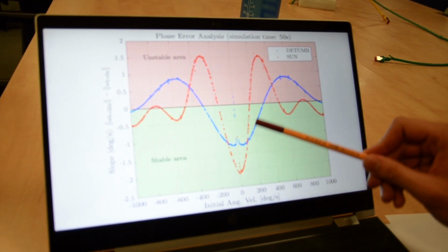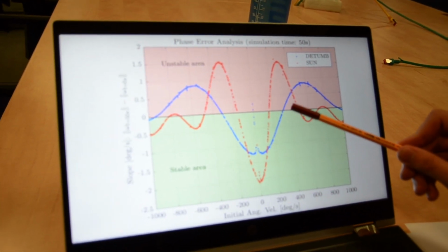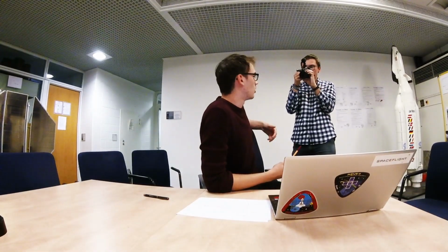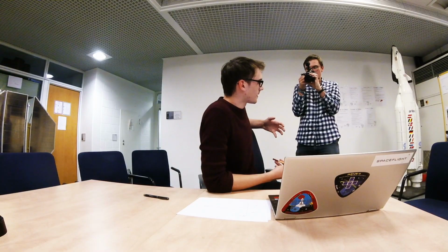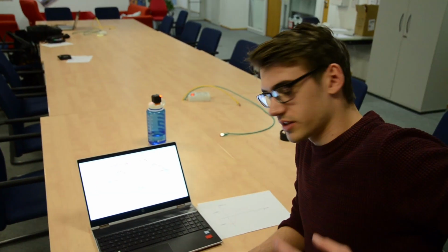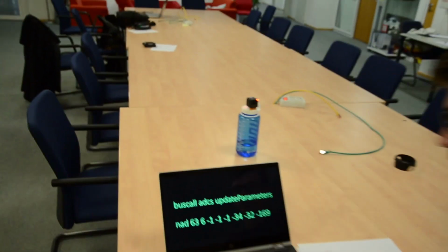Here we are still in the positive, stable part, and now here something is happening, and we need to pretty much change the signs of our ADCS system or magnetometers to make Move2 think it's moving in the right direction again, and basically do the opposite of what it actually wants to do. And this is what command Z does. And command Z looks something like this.